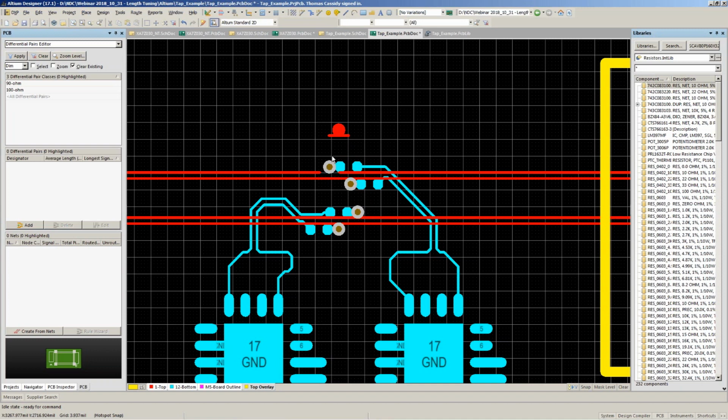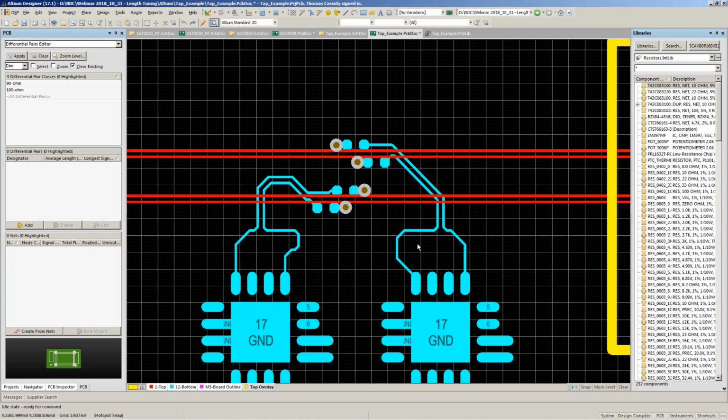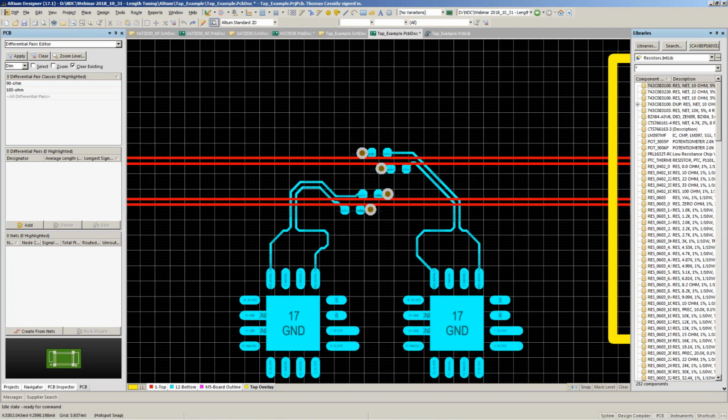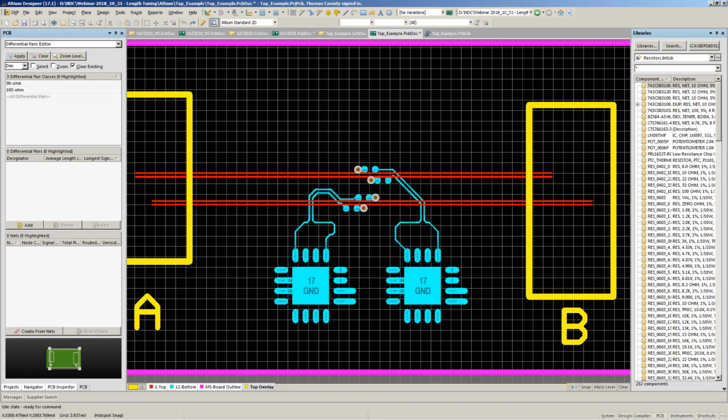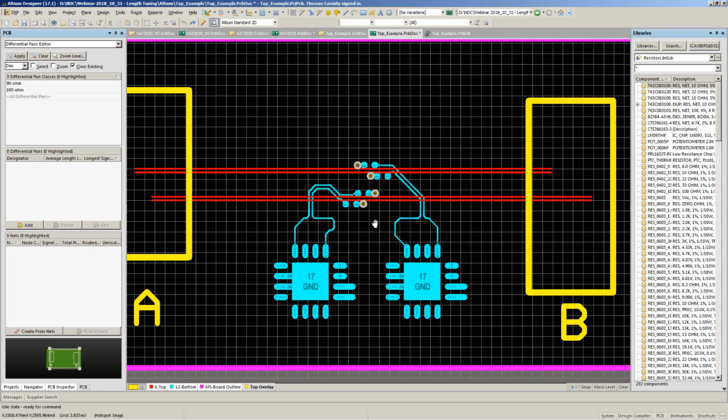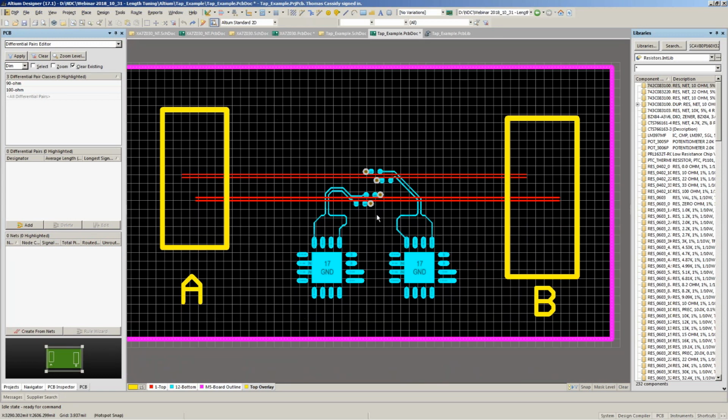And you can see the via that I left in place. And the blue pads are basically my capacitors to decouple, and then I just go down here. And you can see I've already done some length tuning on these guys so that both of these legs are the same. So anyway, this is a real-world example of sometimes you actually have to add in net ties and use the differential names as opposed to getting rid of them, which is what xSignals is usually used for. So I think with that, I'm going to go ahead and turn it back over to Paul.